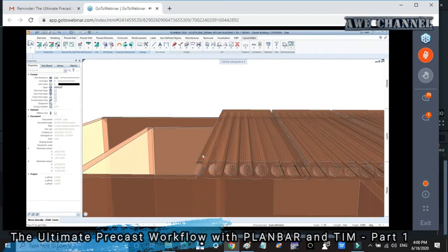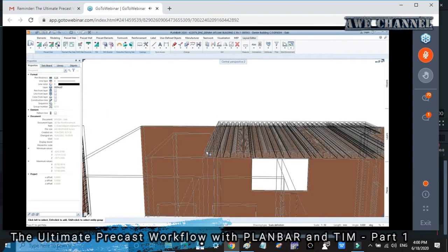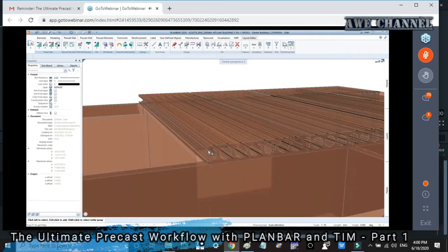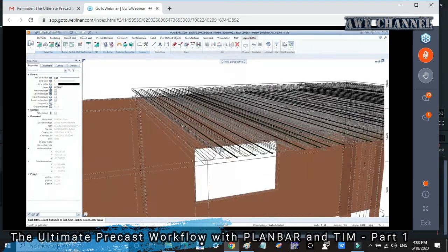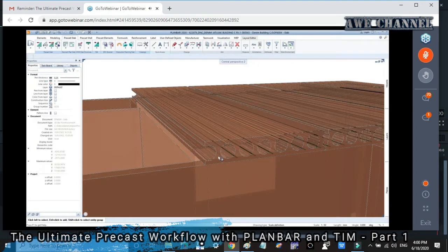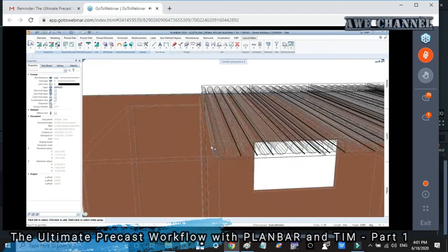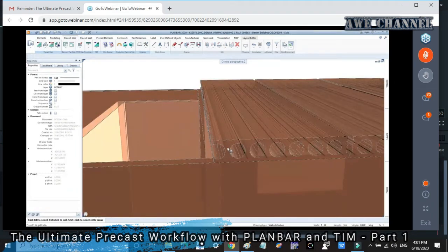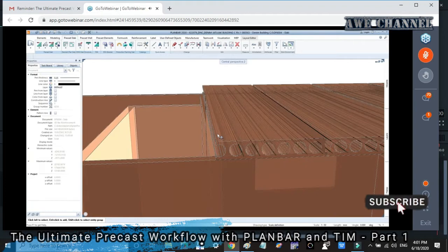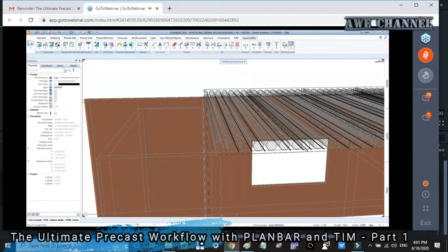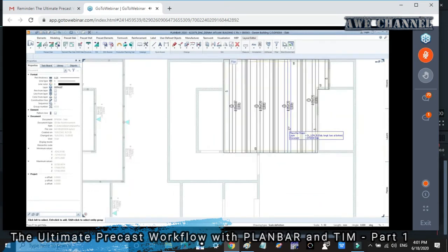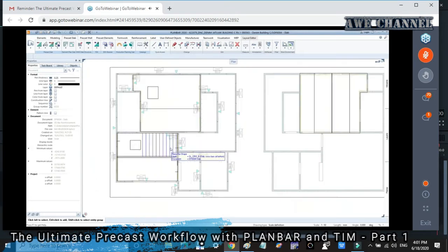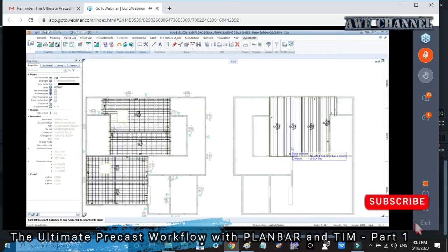The cutting will follow the rules or conditions of your configuration, because we do not allow you to cut your hollow core at the web of the hollow core, right? But this is not within the restriction of the rules. That's why the system is showing the cutting at this area. Okay, it's the same actually with the slab elements.